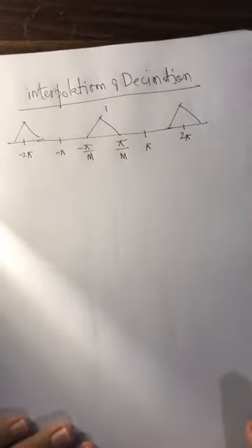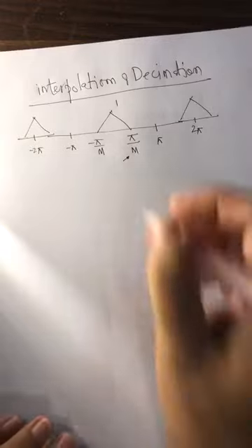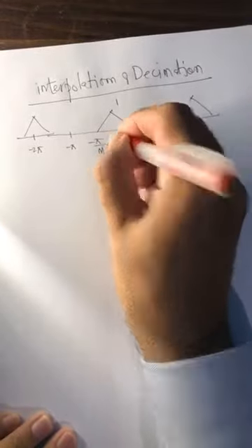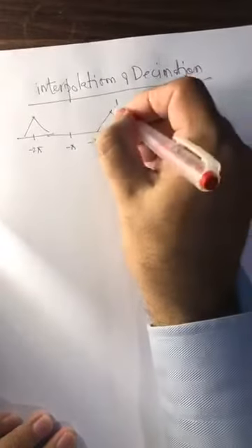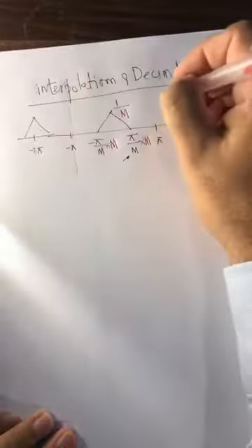Usually your spectrum will look like this, and this gives you the comfort that you can basically throw away samples. In decimation, you multiply this by M and you divide the amplitude by M, and you focus only on this part of the spectrum.